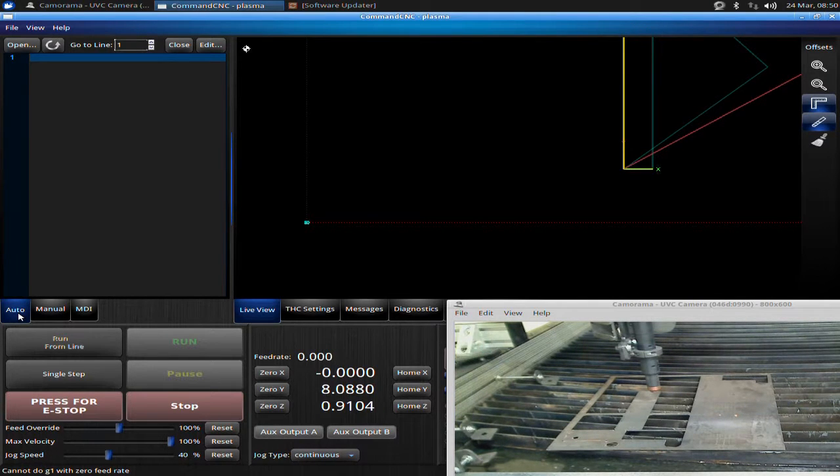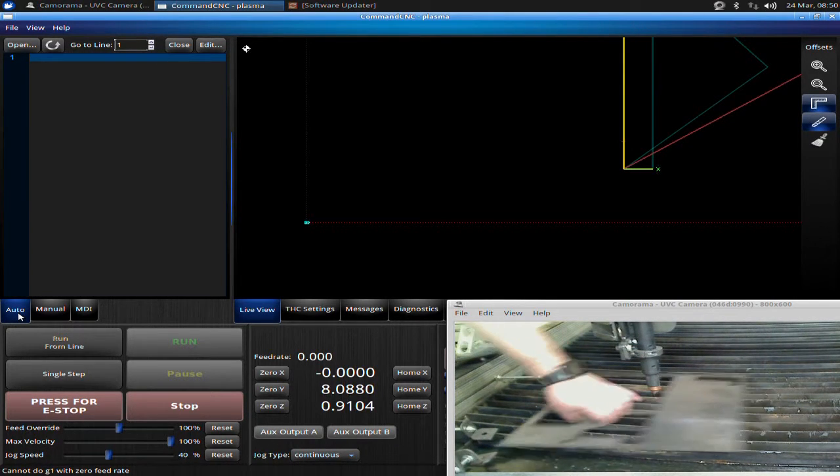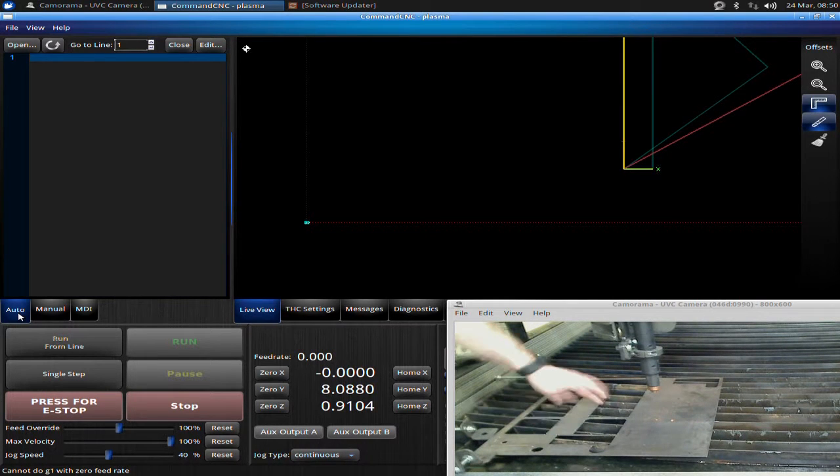So, when you get your table, your material stops will be kind of positioned on one end for shipping. You can spread these out, loosen these up, slide these down, and then position them down along the table so that basically you can line a piece of material up against it. And the beauty of this is it allows you to position your material in the same spot each time. Okay.